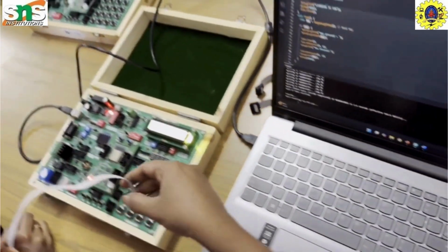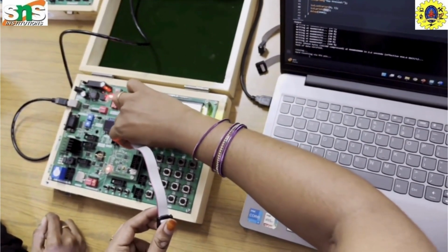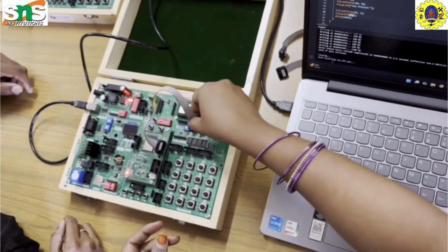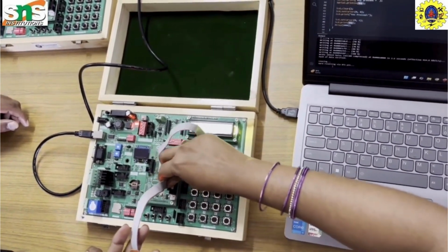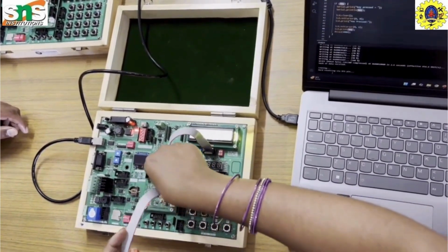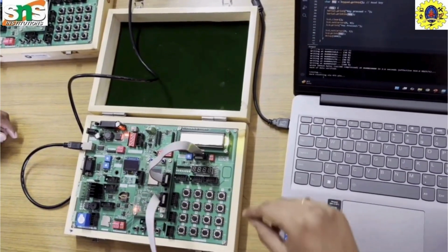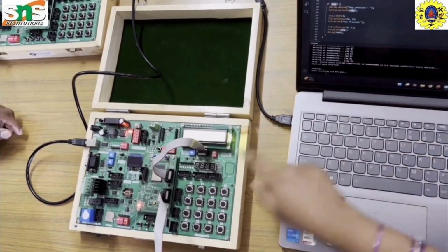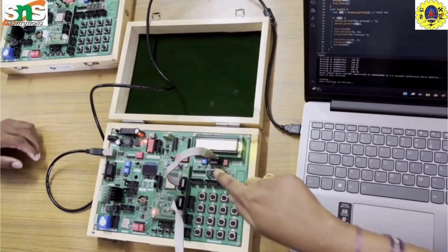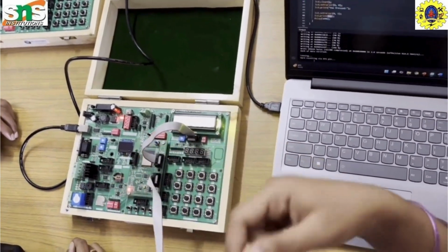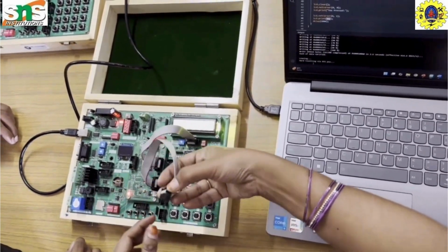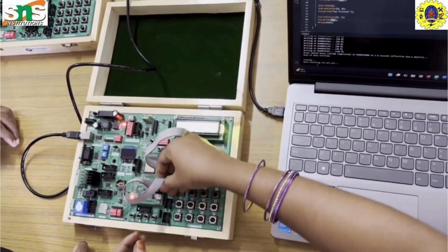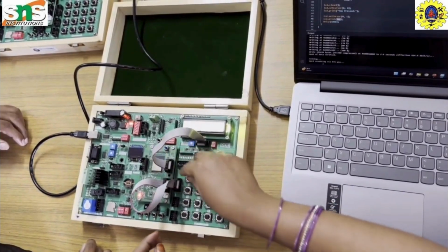Now what I have to do is hardware interfacing. Now I am going to interface my port 2 with respect to my LCD screen, and port 3. You may have a doubt whether I have the same ports to be connected. Yes, because I have configured the respective pins in my program. If you want to use port 1, you can change the pins and configure with port 1. So I am connecting port 3 with my SV5, which is nothing but my 4x4 matrix.